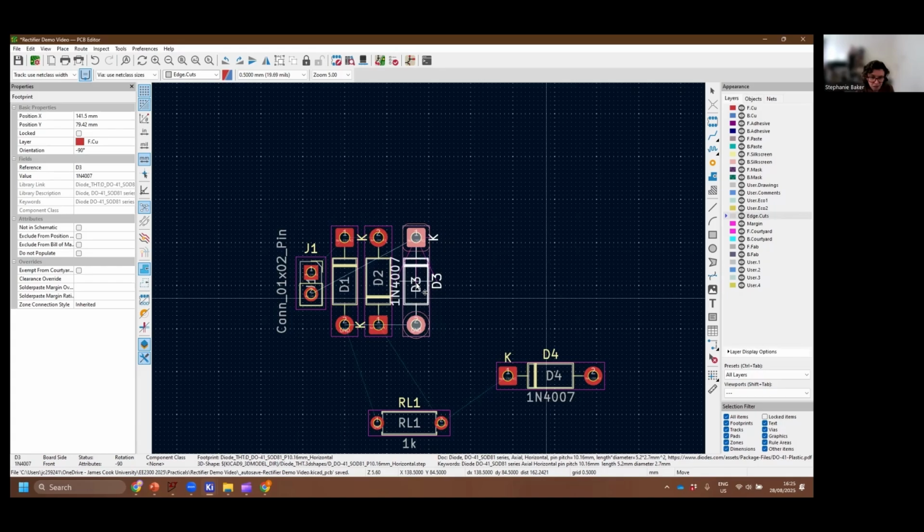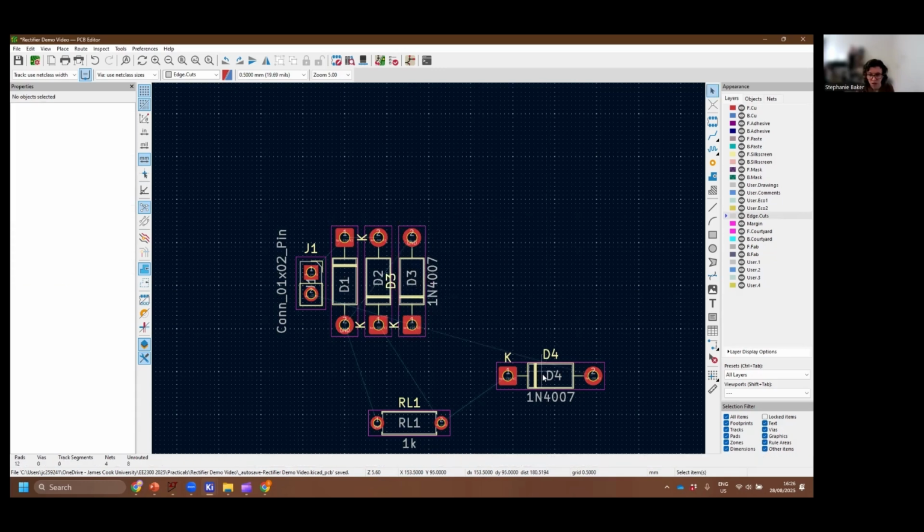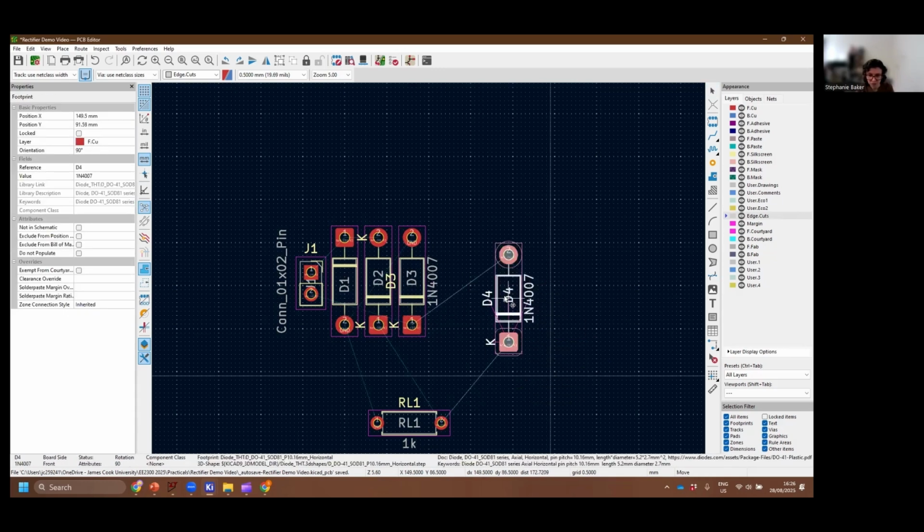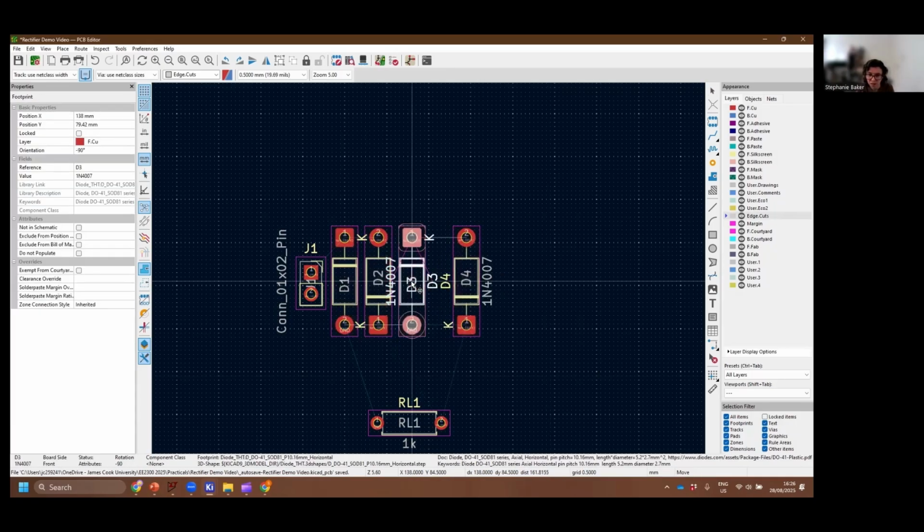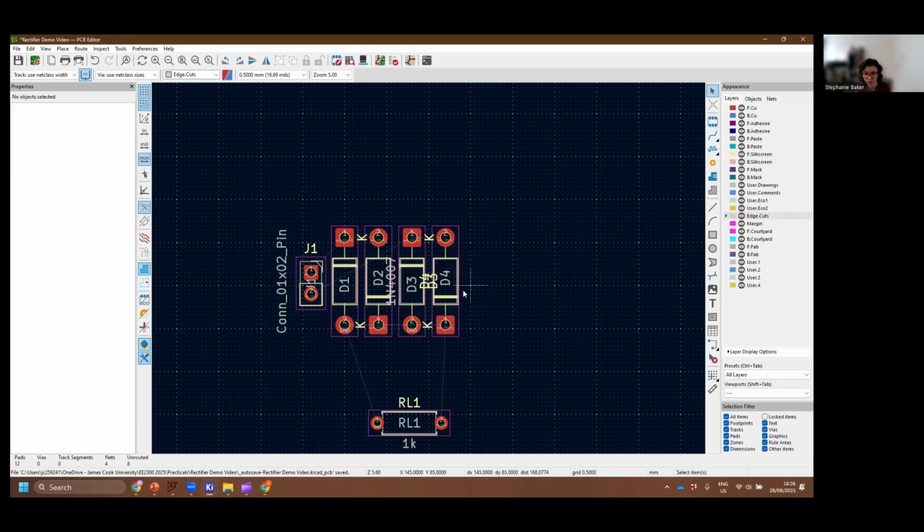And yeah, it's telling us we can connect the ground there, but we don't really need to. So I might actually put it this way so that I can connect those nets together. I'll move diode 4 and see if that was a good decision. Yeah, that's a good decision, because then I can just put those together quite easily as well. Oh, actually those tracks are going to overlap, so I'll rotate this around. And we'll see how that looks.